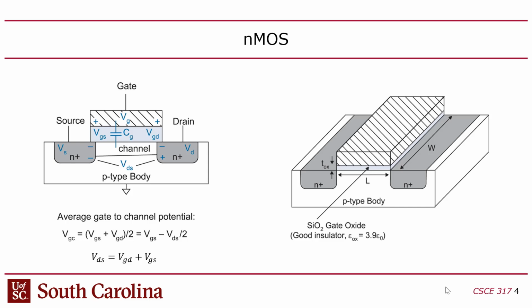But what is the channel voltage? Well, once you turn the transistor on, the channel voltage is actually kind of a gradient. Once you turn this transistor on and the channel activates and you start getting charge carriers, you've now decoupled the channel from the silicon, and now the channel is literally a connection between source and drain, right?